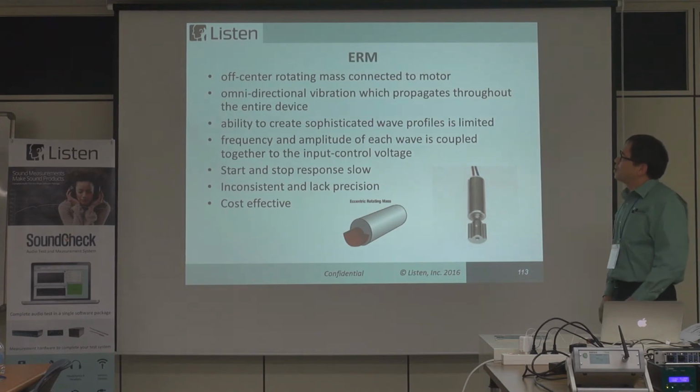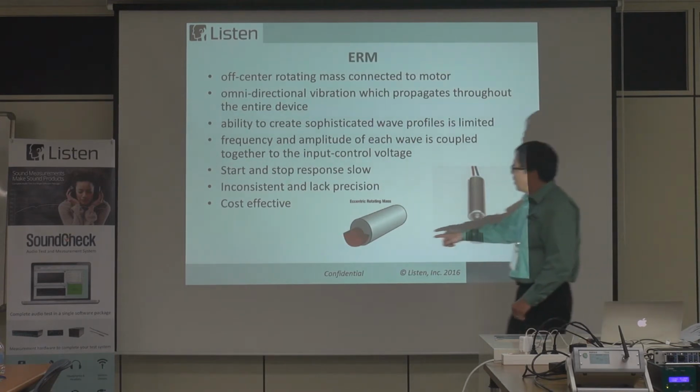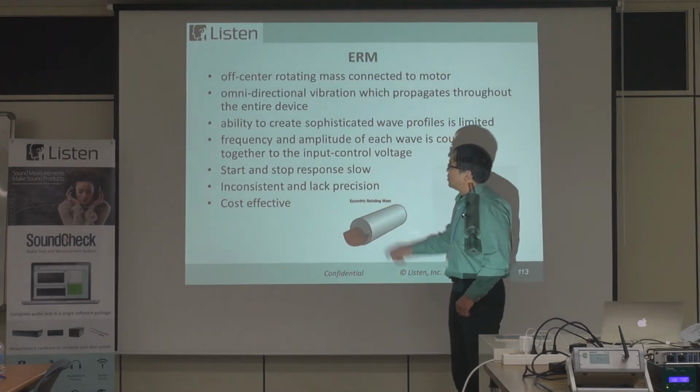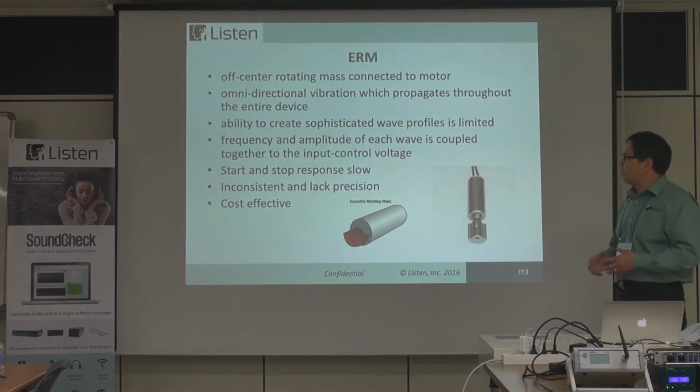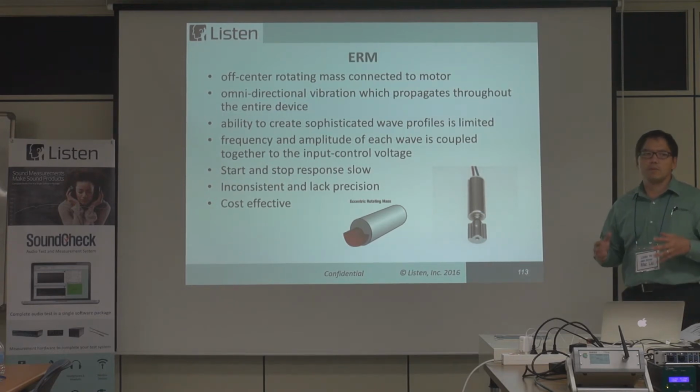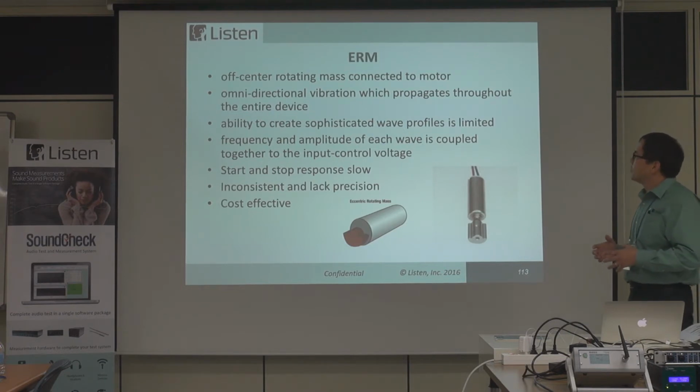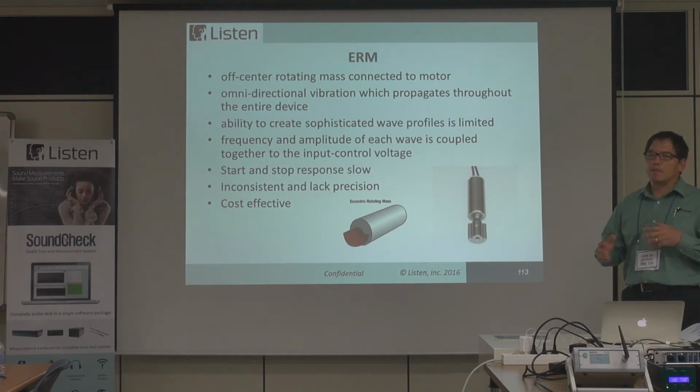So the ERM we talked about, there's an off-center mass attached to a DC motor. And because you can't really control it, the vibration is omnidirectional. The entire device will shake. And you can't really control the amplitude, so you can't create sophisticated feedback.